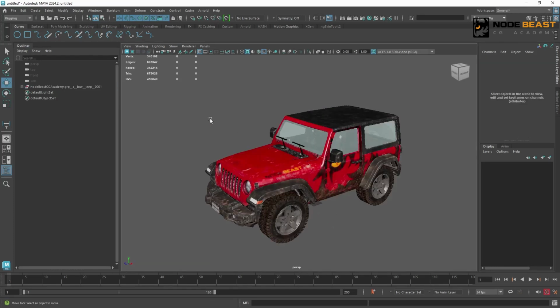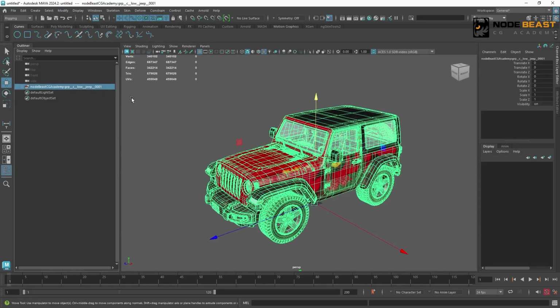For naming, the first thing we need to look at is called namespace. What is a namespace? A namespace is actually just a prefix. Depending on the modeler's import settings, when importing the model, Maya might automatically add some namespaces to the model. And this is a step the modeler needs to clean up when finally renaming all the parts. Let's look at the top level group right now. Everyone will see that this name has a colon before our normal naming format. There's another word in front. Well, this is actually a namespace.